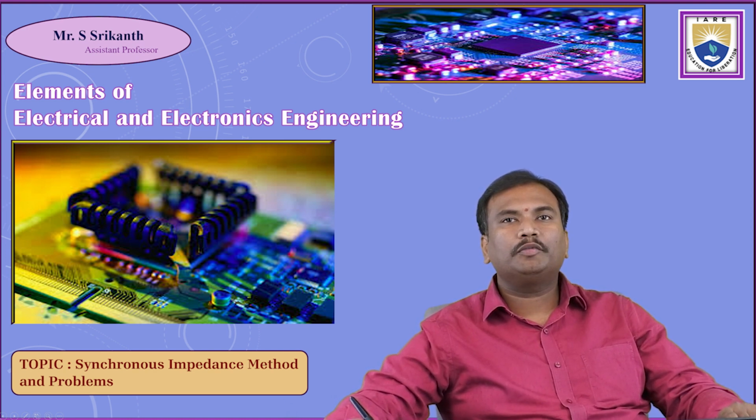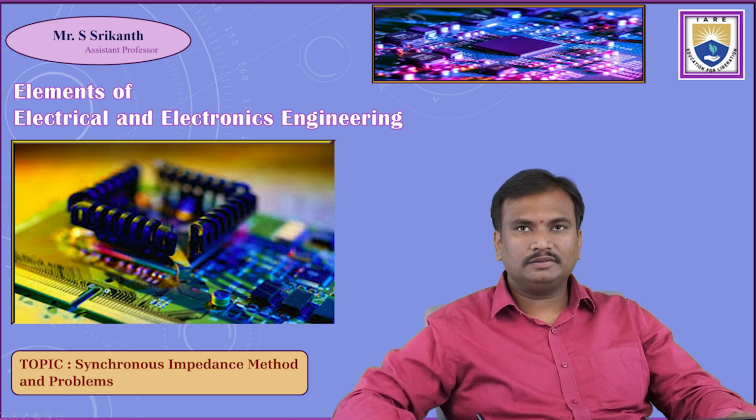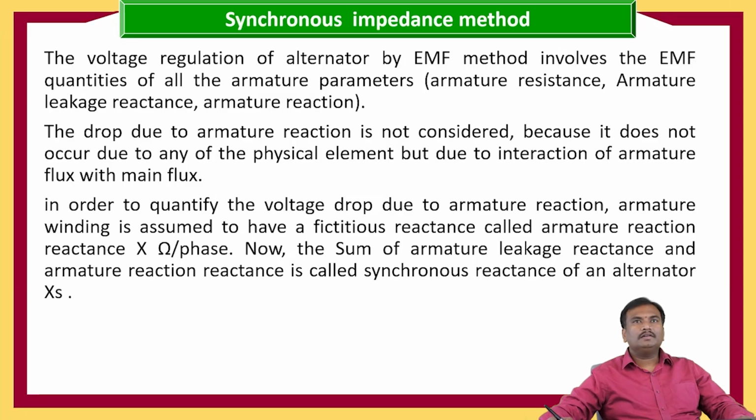In this session, I'm going to discuss the synchronous impedance method to calculate the voltage regulation and problems on this. So first, let us discuss what is voltage regulation. Voltage regulation is nothing but the difference between the no load voltage and the full load voltage. When the load is applied on the generator, what is the change which occurs in the voltage? That is nothing but the voltage regulation.